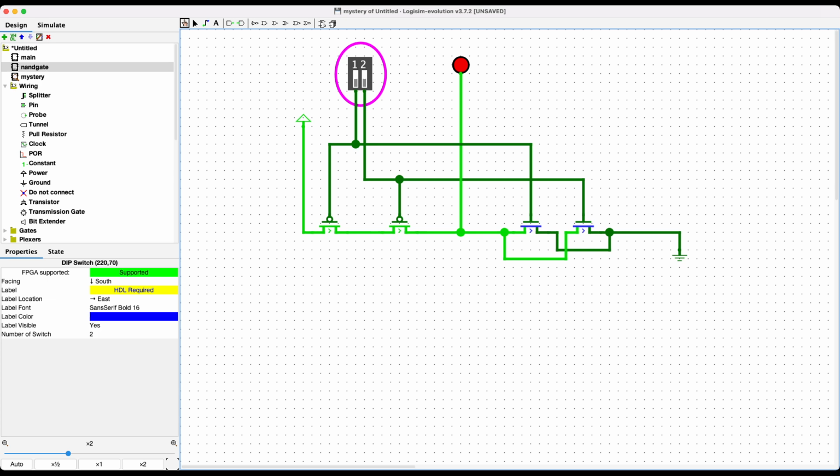Okay, now they weren't originally like this in processor technology. So in fact, early processors, the Intel 4004, used only PMOSs, and the Zilog Z80 used only NMOSs. And the reason was fabrication techniques had not gotten to the point where you could build both of them simultaneously to have similar speed performance and all of that.